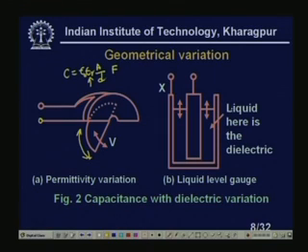So, obviously, the capacitance value will also change. This principle, this method, can be utilized to make a level sensor or level gauge, and it is very interesting that this can be utilized to measure the level of solids as well as liquids.